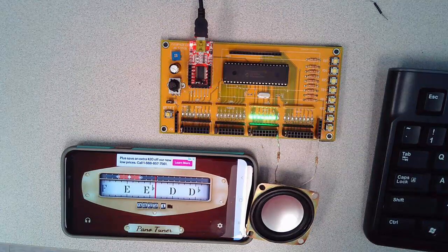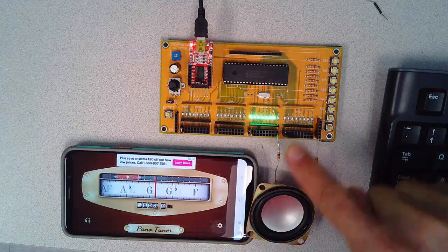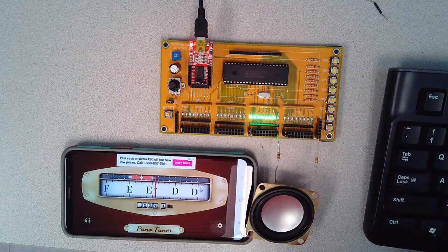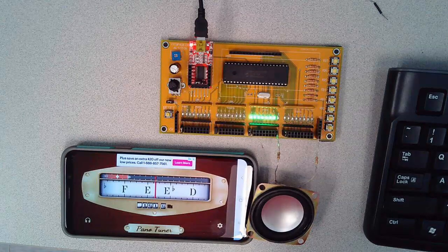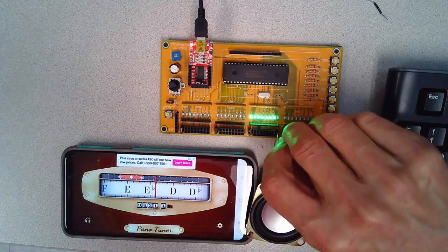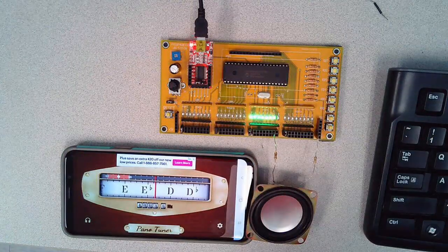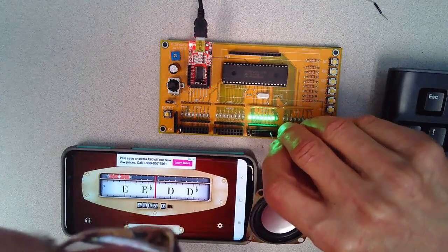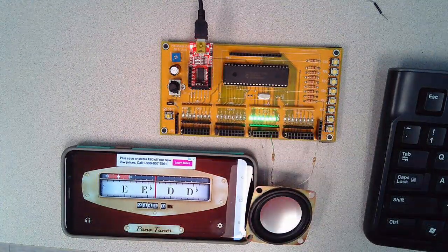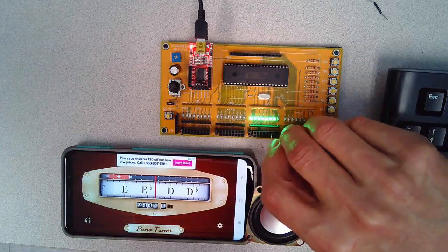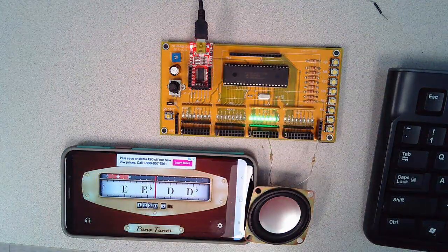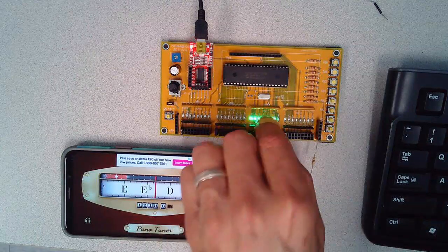Now, if you don't have a voltmeter that measures frequency, I can also use a speaker and the Piano Tuner app on your cell phone. So here I've got a speaker connected to RC0 and ground through 200 ohms. This is the frequency on RC0, 9.7 kilohertz. Divided by 2. Divided by 2. That's another way to measure frequency, which is kind of annoying.